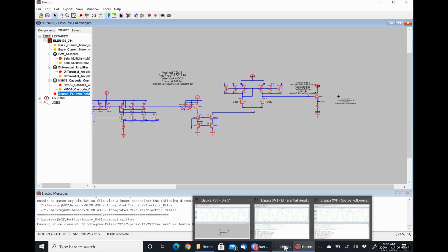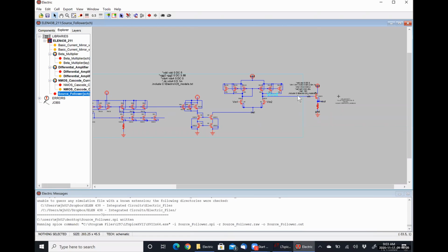The only issue that I would have with that is that because the DC offsets for the input signal and the output signal are different, that may screw things up, which is why I went through and canceled out the DC offset every time. Because the output signal of our differential amplifier has a DC offset of somewhere around 4.